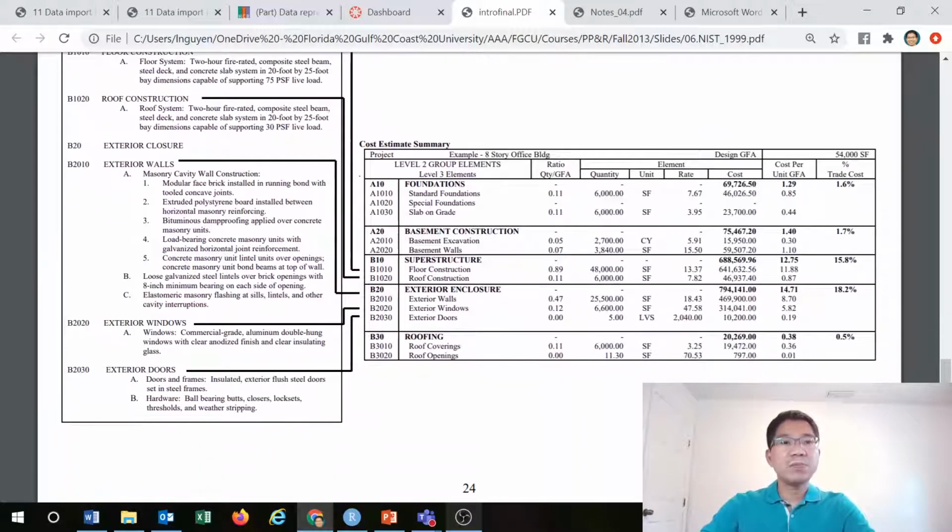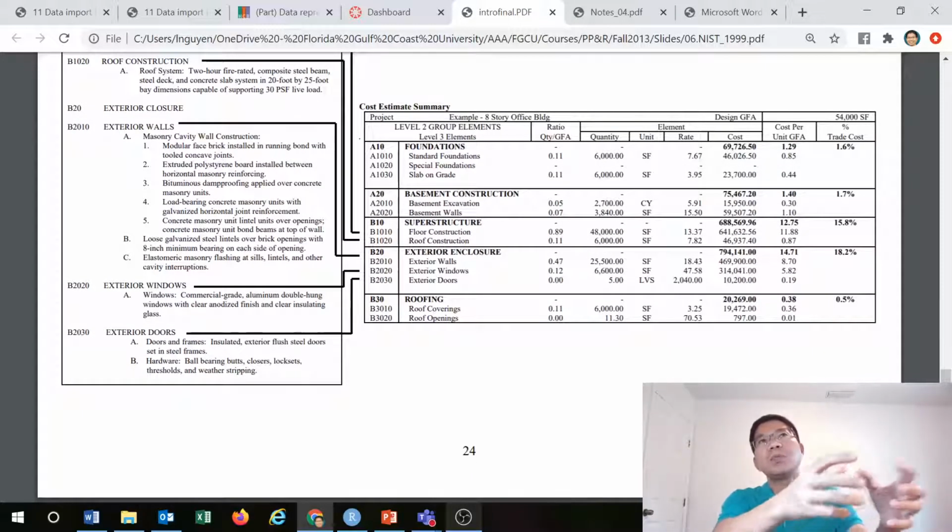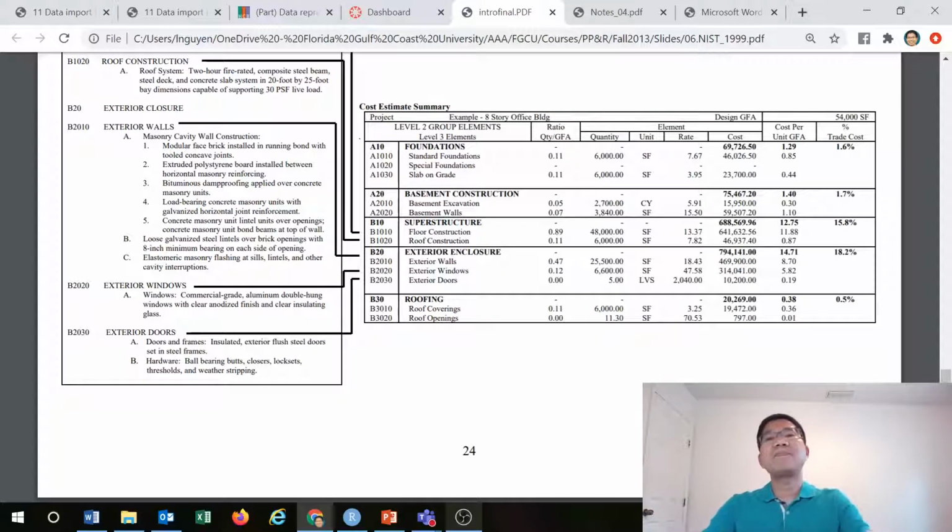For example, if you have exterior wall, it gets linked to exterior enclosure, and we have all the items, have the quantity, the unit, then we can determine the cost. So that is basically pulling out each system and fitting it in. So one advantage of this method is we are able to replace one system with another. Something I told you, like if clay tile for the roof is too expensive, then you can replace it with the asphalt shingle without making significant changes to other design components.